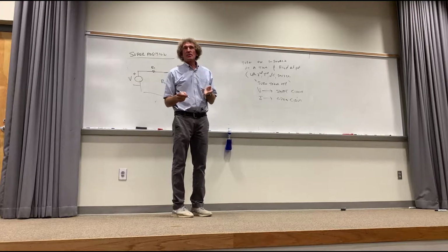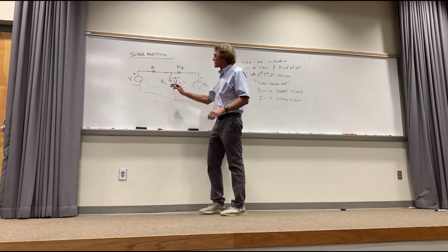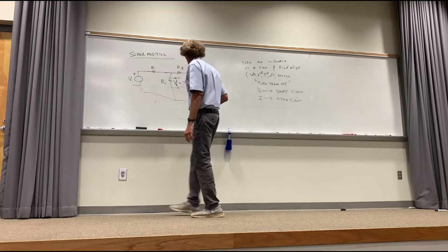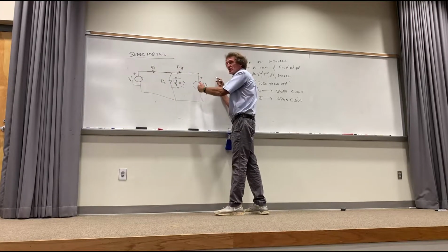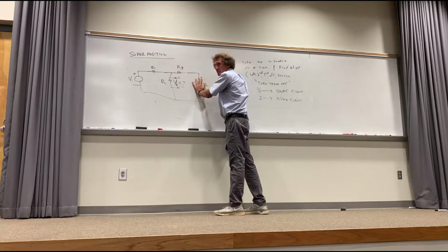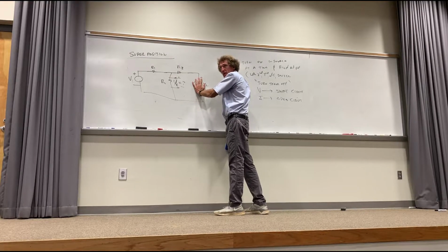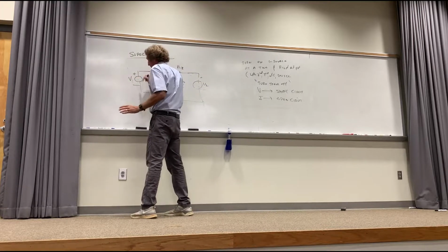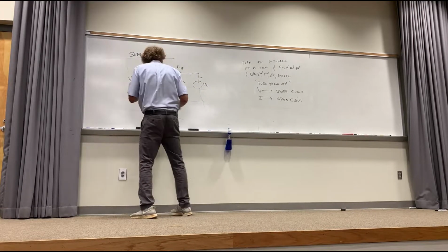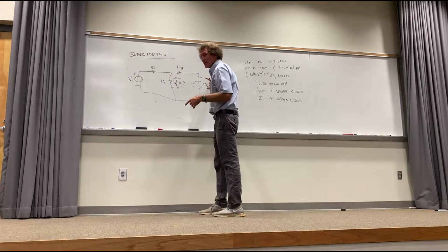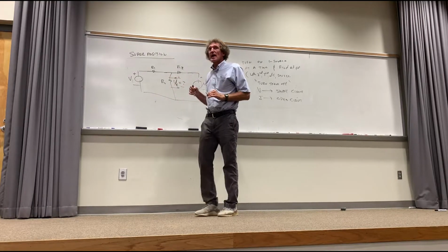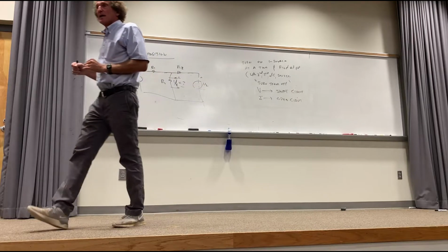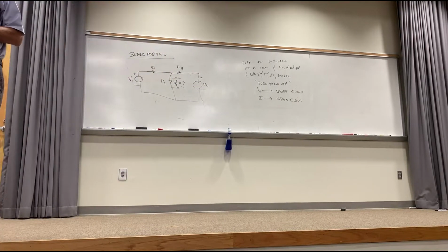And here's really what you do. If I want the voltage here, I start with this source, call it V1. I turn this source off, I make it a short circuit. Got it? Then I solve for this voltage. Follow me? Next, I record that voltage that I got there. I turn this source off, make it a short circuit because it's a voltage source. I energize this one, and I find the voltage here. Then I add those two voltages together, and it will be the actual voltage that occurs there. This is called superposition. It's a useful technique when you've got really wacky looking circuits.